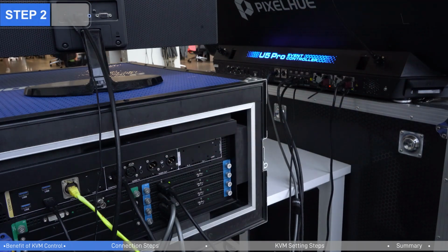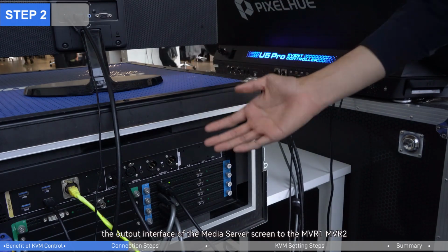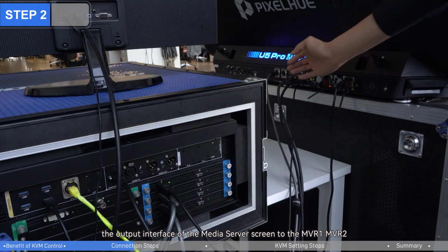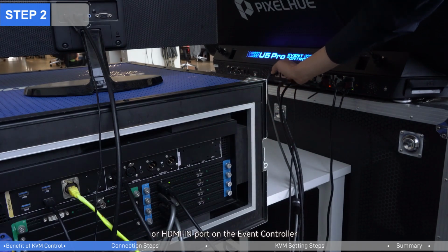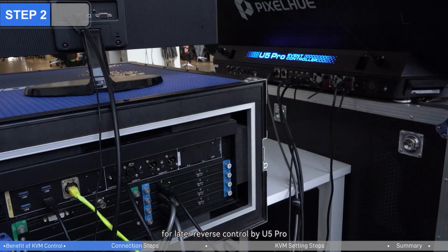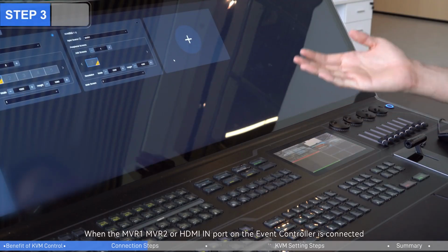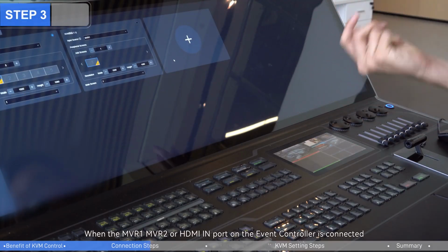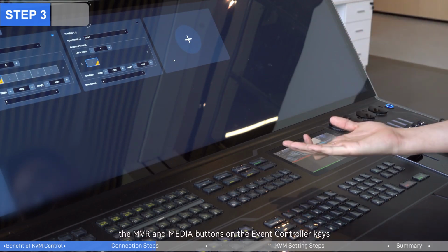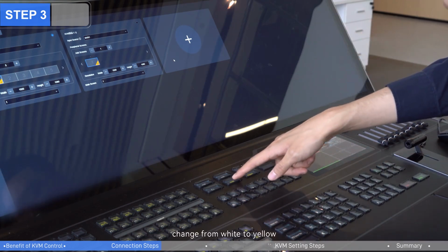Step 2. Use an HDMI cable to connect the output interface of the media server screen to the MVR1, MVR2, or HDMI import on the event controller for later reverse control by U5 Pro. Step 3. When the MVR1, MVR2, or HDMI import on the event controller is connected, the MVR and media buttons on the event controller keys change from white to yellow.